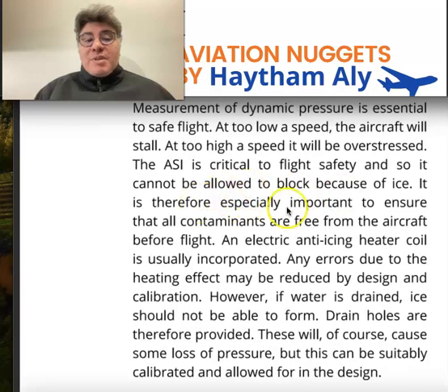It is therefore especially important to ensure that all contaminants are cleared from the aircraft before flight. On the ground, especially in bad weather or icing conditions, or if we are in a country that has insects or flies or sand, we must put on the pitot cover. And also an electrical anti-icing heater coil is usually incorporated in the pitot tube. Any error, everybody, due to the heating effect may be reduced by design and calibration.